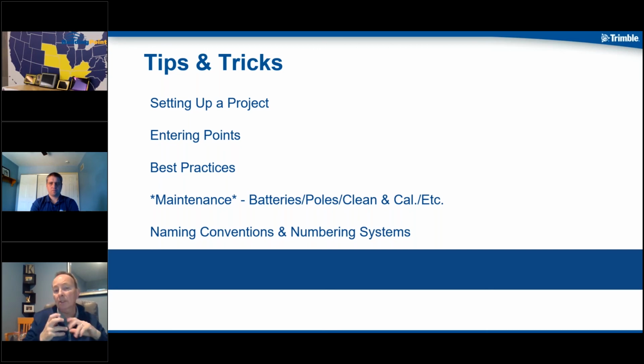We recommend at least three or more points for that resection setup. What you're going to see is that if, for instance, maybe you're using a column line intersection as your setup, but for whatever reason, that snap line that you're using as your setup may be rotated just ever so slightly. What you're going to see is all the data that you're out there trying to lay out is going to be rotated slightly. So because of that, when you can use that third or fourth control point, bring that in, you're going to get rid of that rotation. It's going to snap to that new location and get you a much better solution for your location, okay? So that's a best practice.